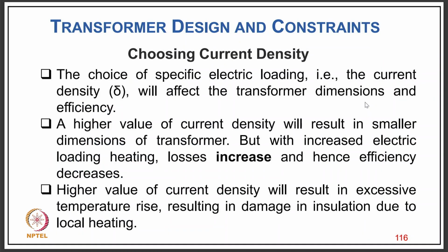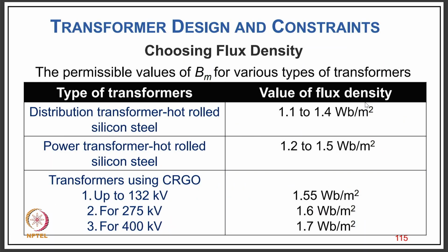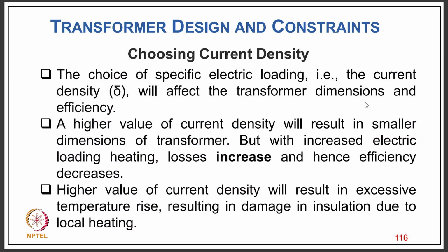So you can see that as the voltage rating as well as the power rating goes higher, we use a higher flux density so that the size of the transformer is reduced. Of course, we have to use better cooling.